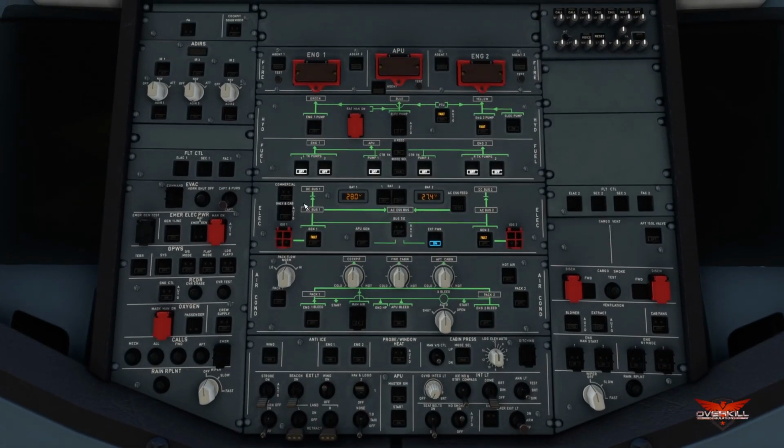And actually we'll step upstairs. We'll turn our seatbelt signs on. I'm also going to start the APU and as well as bring up the beacon light and turn on our fuel pump so we are ready for engine start when it's time.